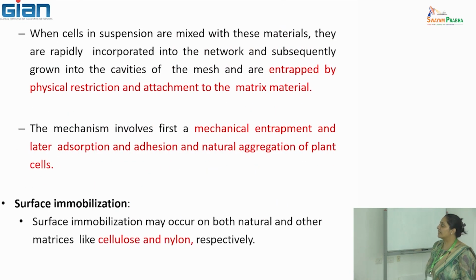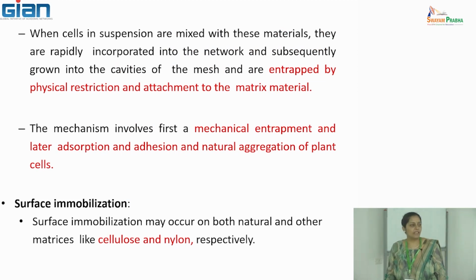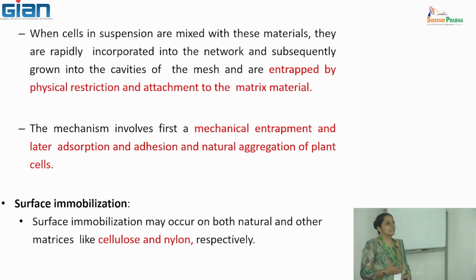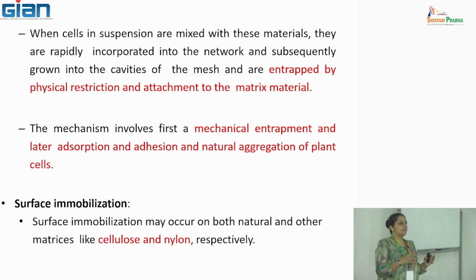Now, coming to the reactors which can be used for immobilized cells, and how they are different from stirred tank reactors. They are generally packed columns. So, these packed cell reactors have a limitation of a large pressure drop, so how do we improve the mass transfer requirements in these? The improvement in mass transfer is done by converting these packed bed columns to fluidized bed columns.